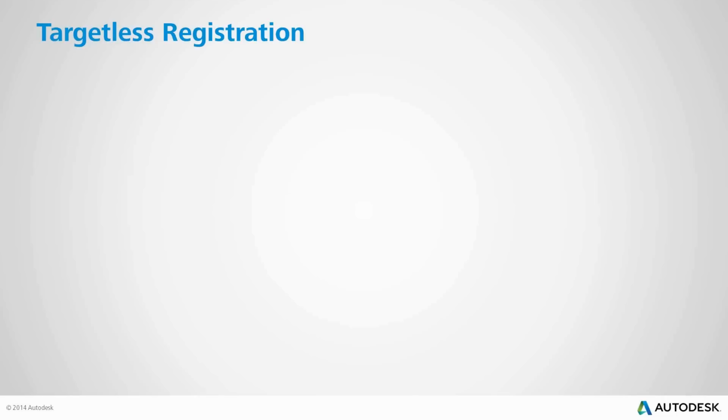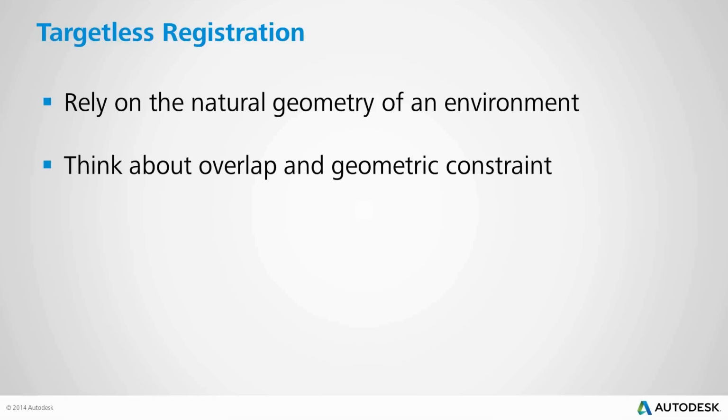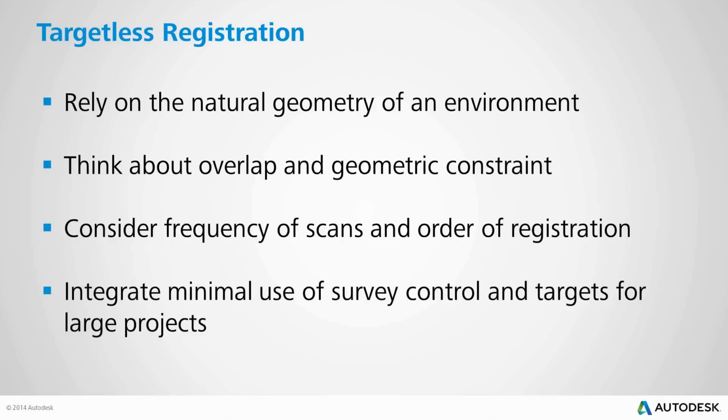Okay, so that's basically it. Again, in summary, we're relying on the natural geometry of the environment, not just a handful of targets. Obviously, think a lot about your overlap and your geometric constraint to get the best result possible. Think about how you're scanning and what your spacing is and how you're registering. And then, for large projects, think about some minimal use of targets and surveys to help assist with that registration.